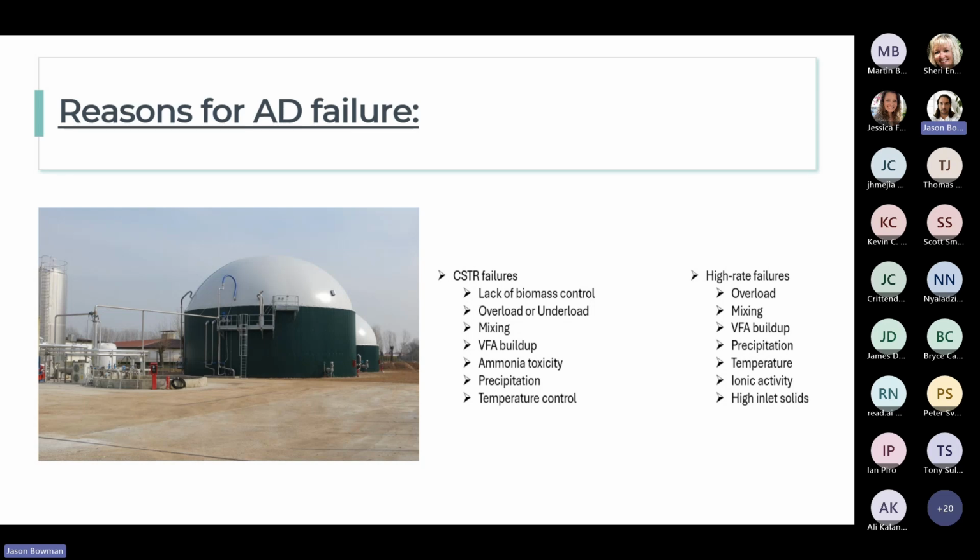And then number 6 really comes back to precipitation. So we often proactively combine precipitating magnesium ammonium phosphate, that is struvite, with the recycle streams in these recuperative thickening processes so that we can minimize the precipitation reactions inside of the digester itself. In other words, we can really address struvite removal external to the digester in combination with a better biomass recirculation.